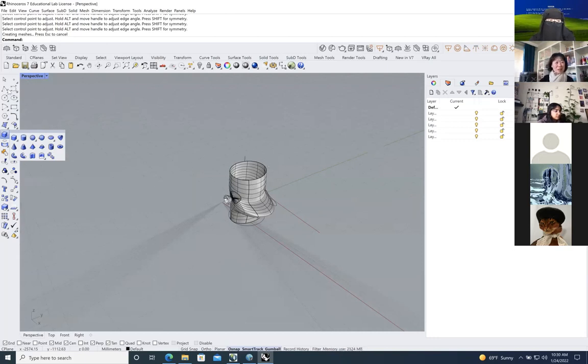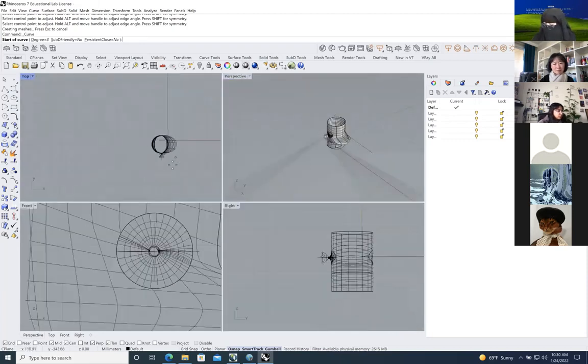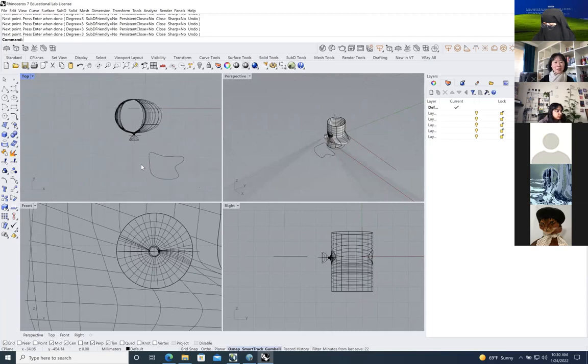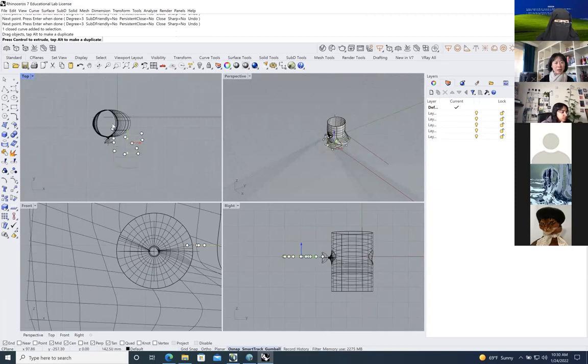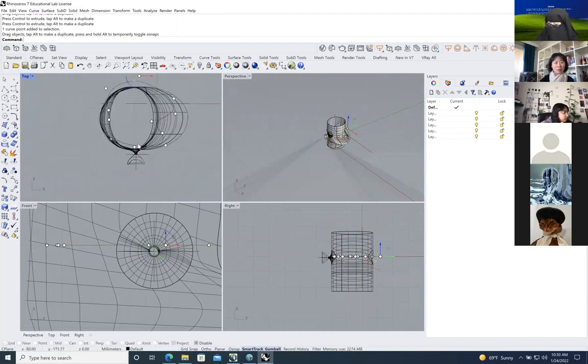So I'm going to create a curve. Okay, so I'm going to use this curve to be the hair for the head. I'm roughly matching it. Be careful not to snap to anything when you do this. I will turn off the object snap, because otherwise they go all over the place.